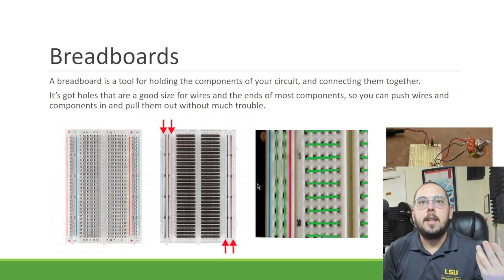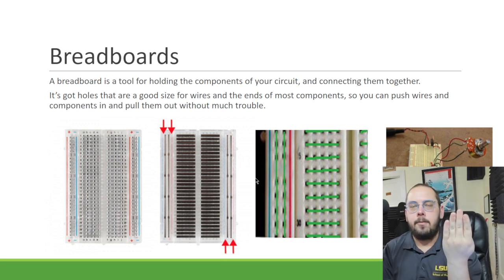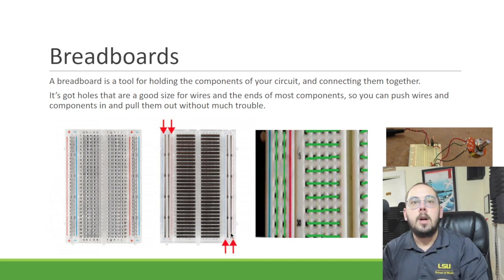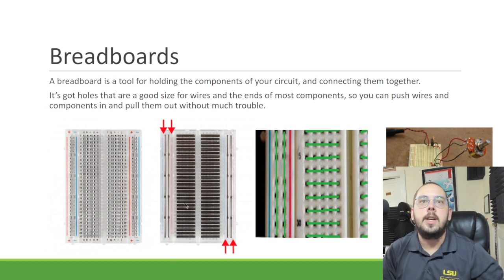The way we tend to line it up, if you were to take your breadboard and flip it over, you would see this metal that's acting as a conductor that goes along the length of the breadboard, and then a whole bunch of these different horizontal ones. So we can put in a bunch of things and connect it. There's the common power and ground along the sides, and then whatever we need, it's a little more isolated.